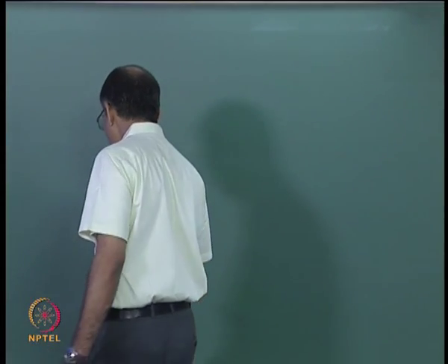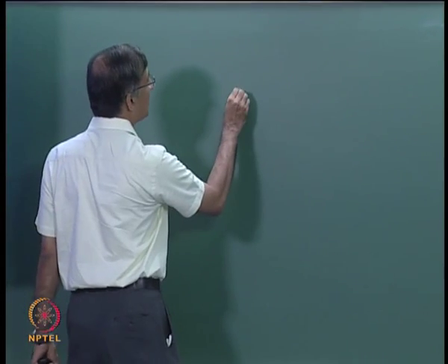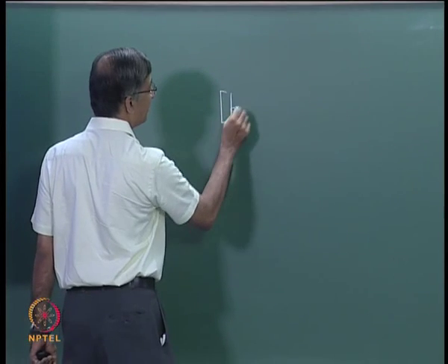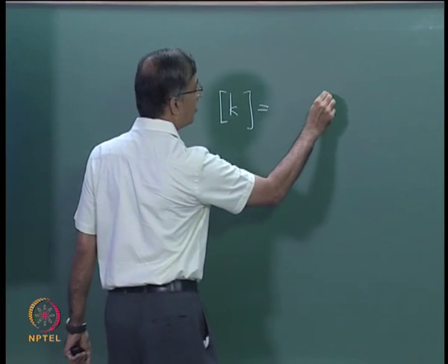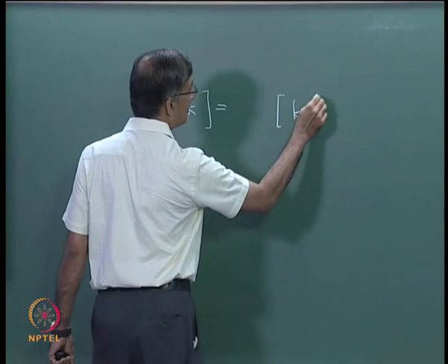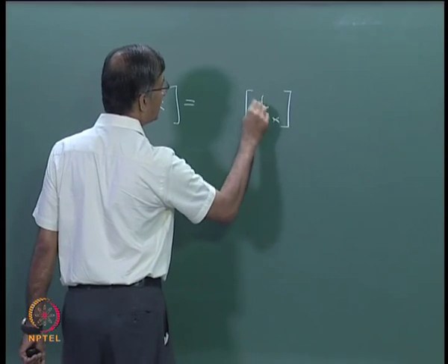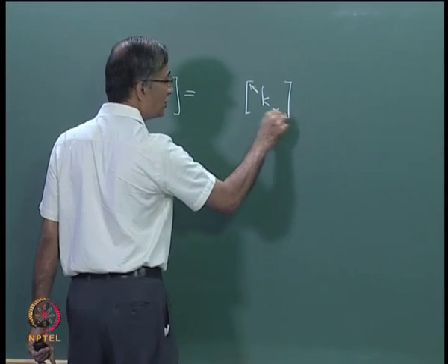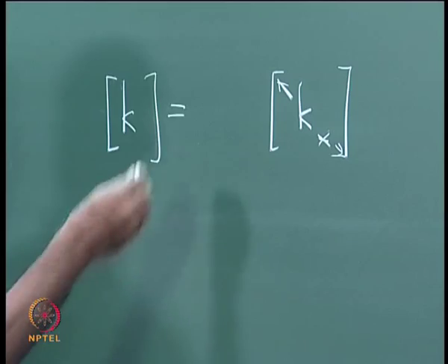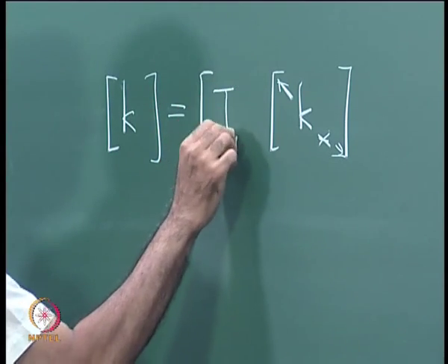It is. Okay, you are not thinking. I want to generate the structure stiffness matrix K, and I want to do it in terms of this matrix K star, which is a diagonal matrix as shown there. That is all. So I do TD transpose.